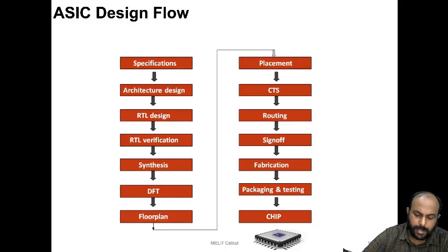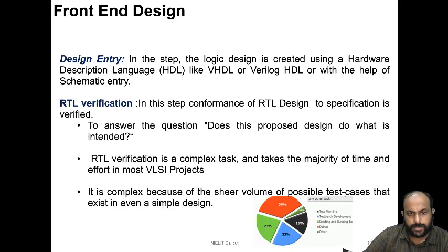After RTL design verification is done, it is subjected to something called synthesis. Synthesis is basically the process of converting your design into a structural equivalent. These two steps, RTL design entry as well as RTL verification, along with some portion of synthesis, can be called front end design, because at the front end itself people will often verify the design on some prototyping platform like an FPGA before we take it to the backend design for the ASIC flow.